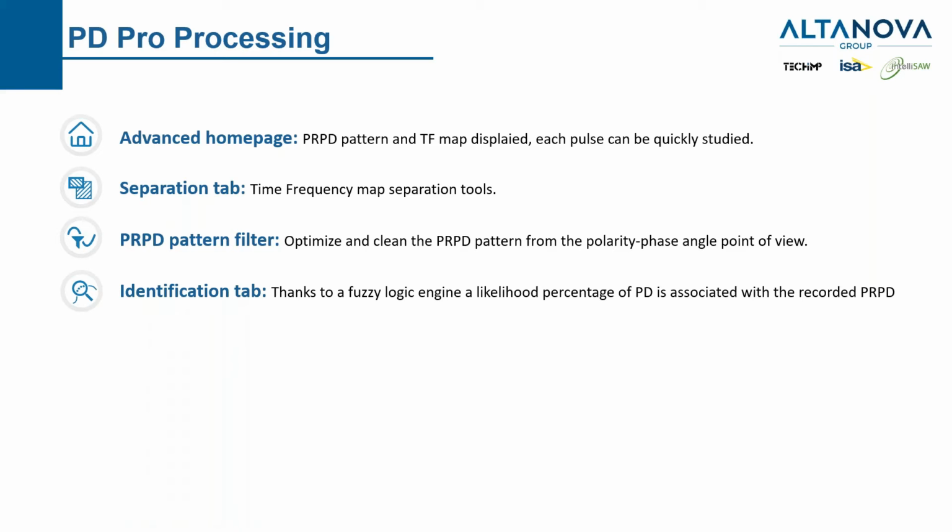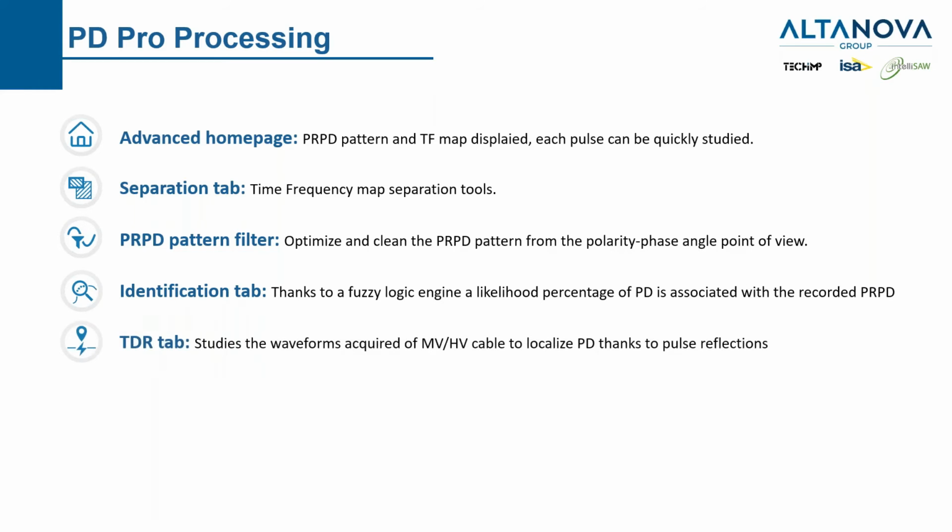And we have also a second stage of this analysis, depending on the license, where we can statistically associate the PRPD pattern to the defect typical of the asset under test. So we have to define if it is a cable or a machine, and the system will try to correlate the current data with one of the typical defects that we can have in such assets.